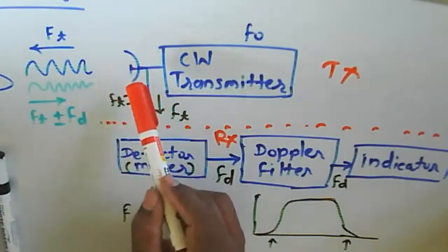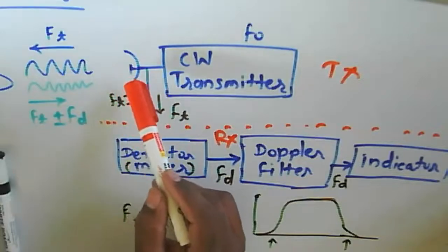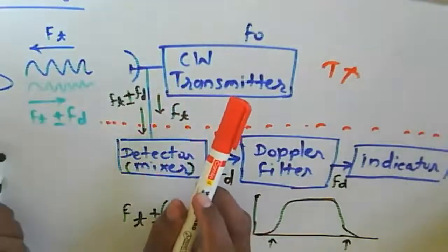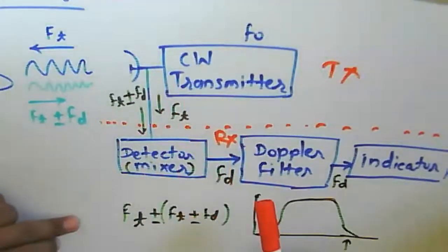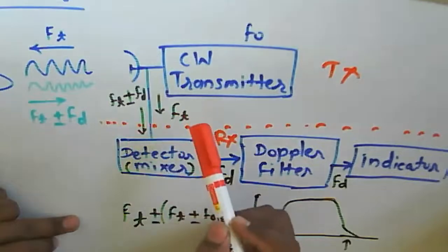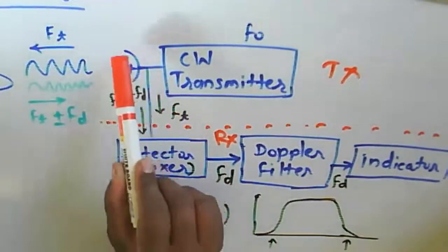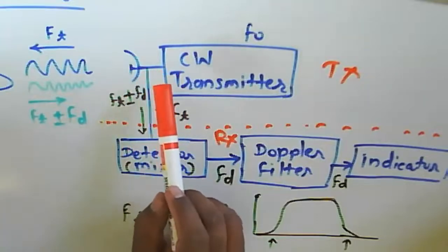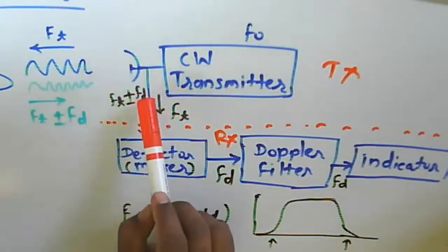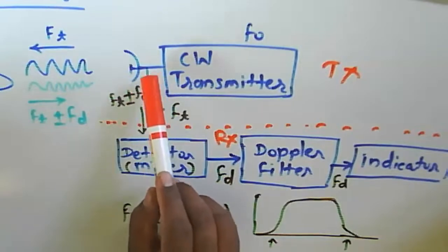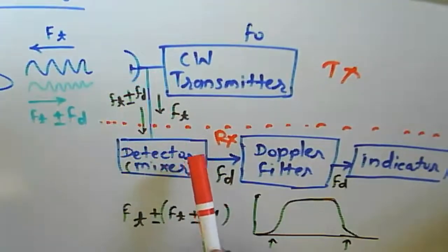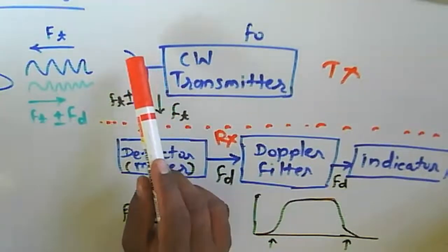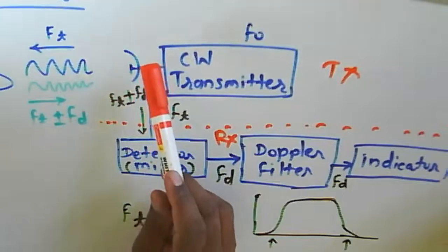So we can use a circulator or a T junction here, which serves both the transmitter and the receiver. You have seen the microwave T junction, which is used for the purpose of isolation. At the time of transmission, that device will transmit. At reception, that junction will forward the signal only to the detector. So a single antenna is sufficient for both the transmitter and the receiver.